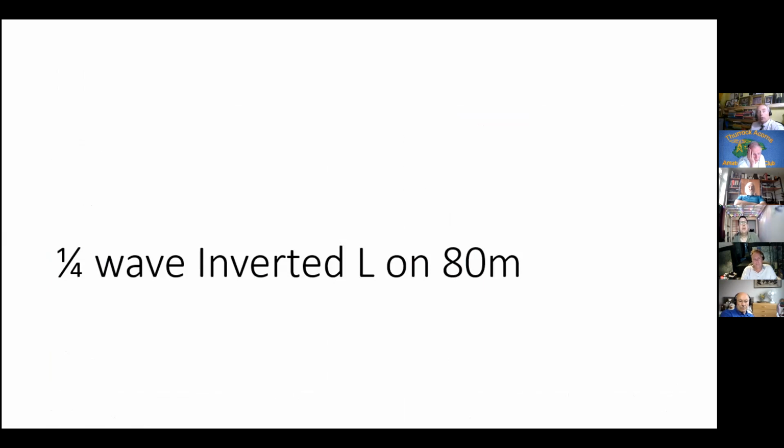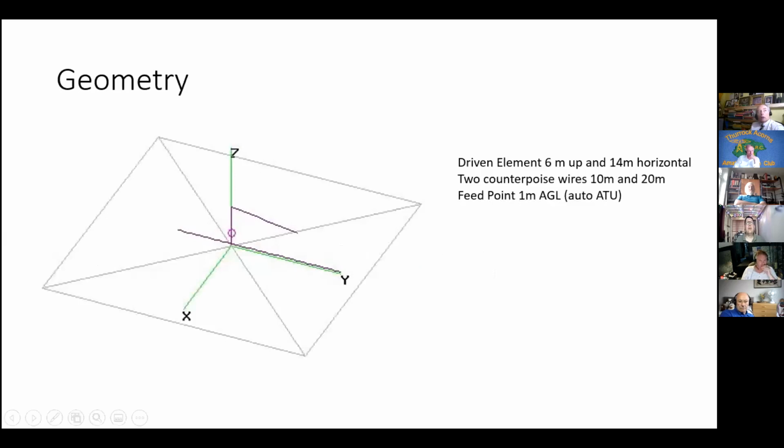A lot of people use inverted L's and think that they are much better than dipoles, particularly when working a mixture of distant and remote stations. So this is a model of one that I did earlier that had two resonant radials, one for 40 meters, one for 80 meters. The antenna, of course, is a little bit shorter than the radial for 80 because it goes up before it goes along. It's a quarter wave on 80. And what I had was a link that I could open to make it a quarter wave on 40. So just lower this end, disconnect the link, haul it up again. And it works quite well.